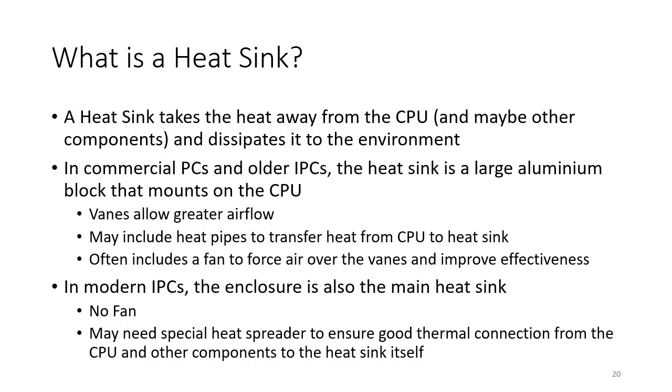We also mentioned earlier the mounting of the industrial PC. If you're mounting an industrial PC on a DIN rail, then you haven't got a very good connection to the actual backplate of the panel itself, so the panel that you install on can also become part of the heatsink. So if you've got a very large enclosure with a solid metal panel, if you can bolt the industrial PC directly onto that panel, that can also form part of the heatsink as well.